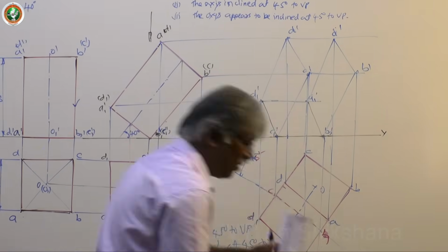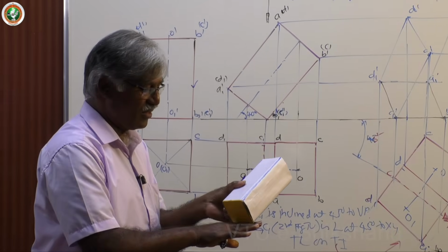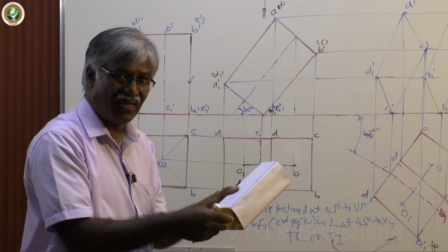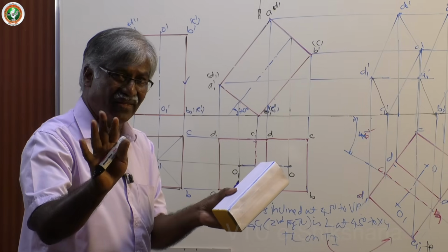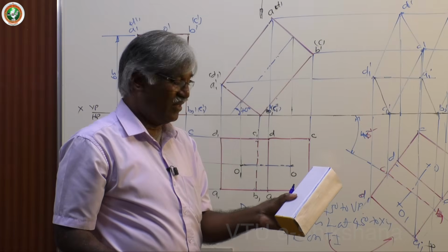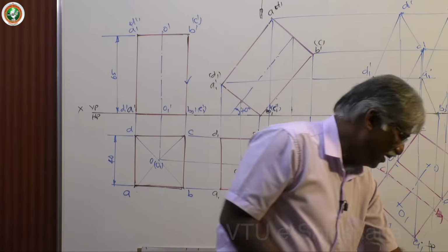So as usual, first position, second position, third position. Which is nearer to you, key surface, base or top face? Both, base. That's the only criterion I need. I don't need anything to complete the front view. I need not refer to any line in the top view. How? It's possible.